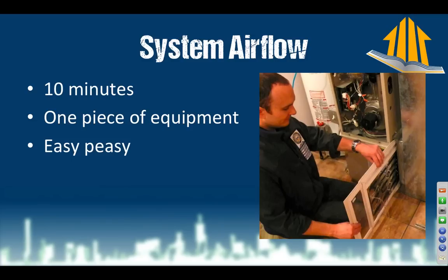You could get the fan curve tables from the manufacturer and use those. You could use a pitot tube and do all kinds of crazy calculations. Frankly, this is the easiest way. This configuration here, where the plenum comes down and then takes a 180-degree turn through the blower cabinet is the worst place to use this piece of equipment, but I at least want a piece of data. Even if it is a little bit flawed, it's better to have data that's maybe not 100% accurate than no data at all.